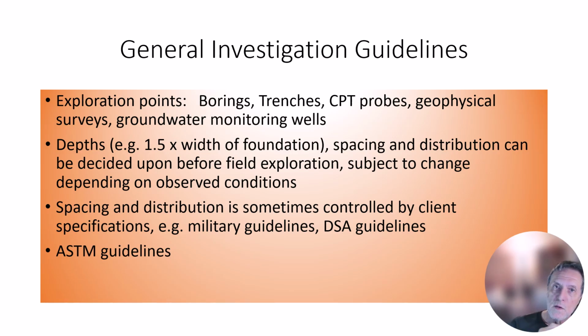So generally speaking, your investigation guidelines will include the mapping out, the selection of locations for borings and trenches, etc. For the depth of investigation, a rule of thumb found in some textbook is 1.5 times the width of the foundation. In practical terms, though, that's not always observed. So if you have a 50-foot wide building, you don't generally go 75 feet. In San Diego County, it's often adequate to go until you hit nice, dense, firm formation.